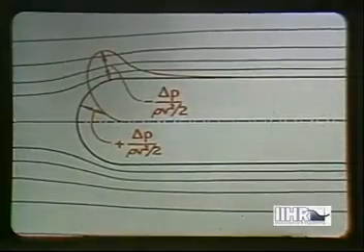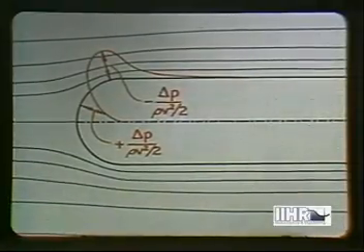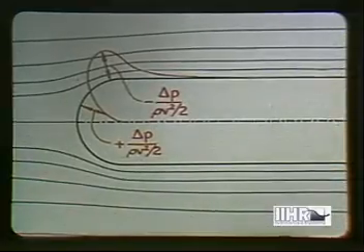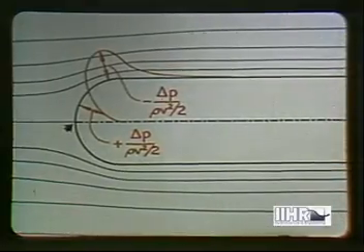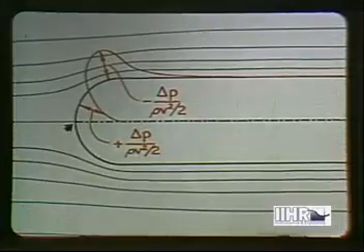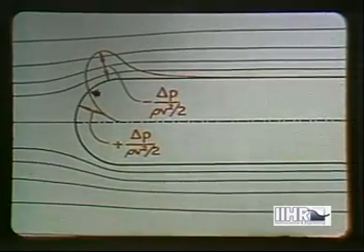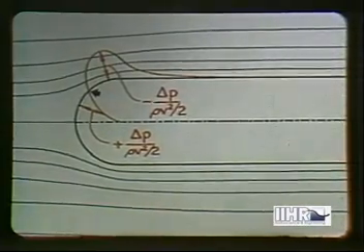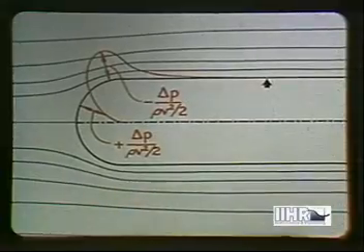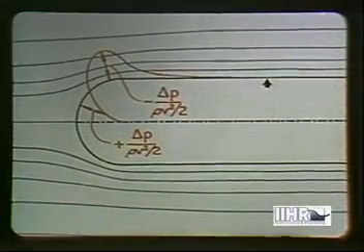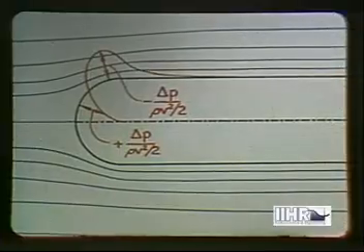For example, it states that as the velocity becomes equal to 0 at the nose of a body, the pressure there will rise by an amount equal to the dynamic pressure, as in the ordinary stagnation tube. The pressure either partway around the nose or far back along the side of such a tube, on the other hand, is that of the undisturbed flow, and the difference between the tip and side piezometer readings is thus the dynamic pressure, as given by this Prandtl-type pitot tube.